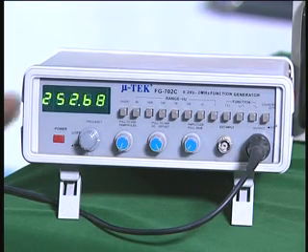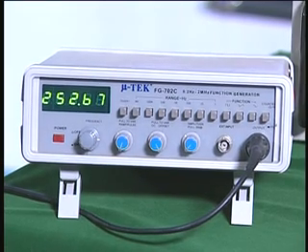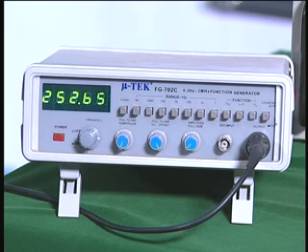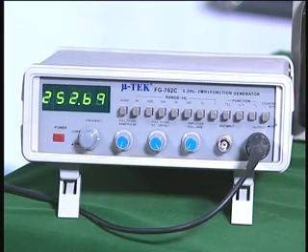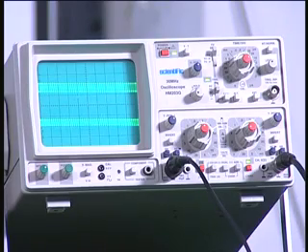Now the bandwidth in this case has decreased, so we can continue and try to do it for a gain of 100. Then what will happen is the amplitude of the output will be very very large, therefore you should correspondingly reduce the input signal so that you can still have reasonable amplitudes of the 2 signals on the oscilloscope. I leave that for you to try on your own.